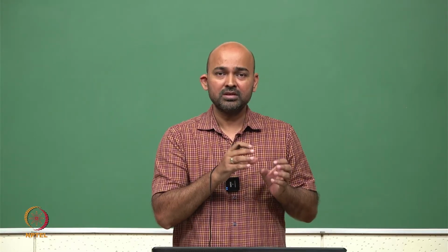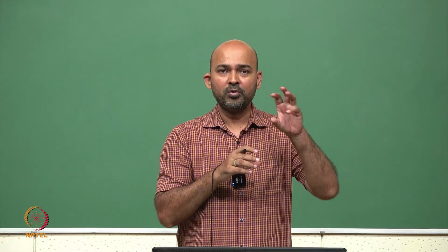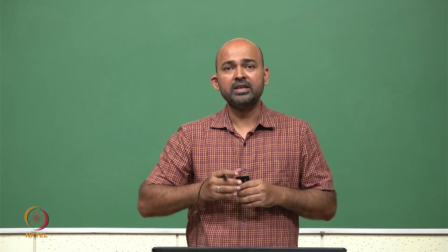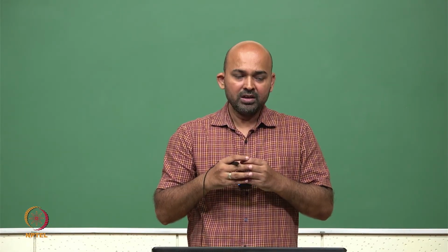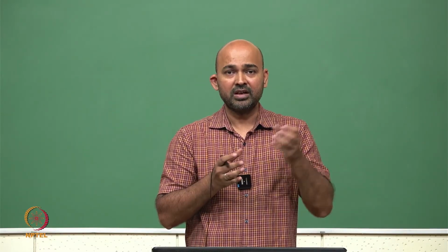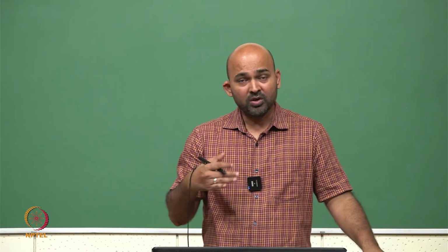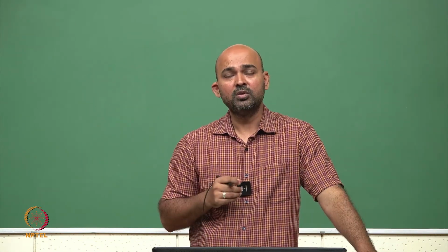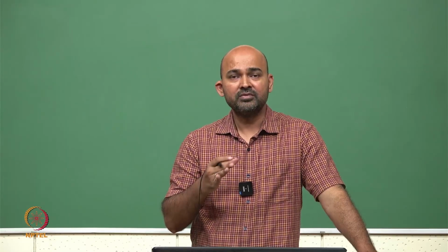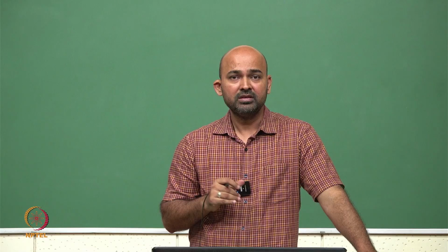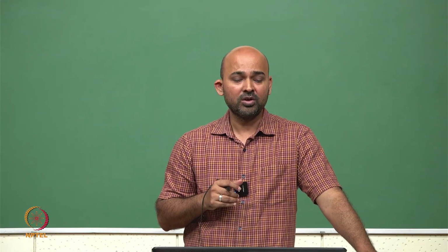However, in static CMOS, we have pull up network and pull down network. So n and n, there are 2n transistors needed. When we need a large number of gates, it means we have more gate capacitance which we are connecting to the previous stage. Because of these extra gates connected to the node, we have extra capacitance which is going to degrade the delay sometimes. So that is one property of dynamic logic gates.